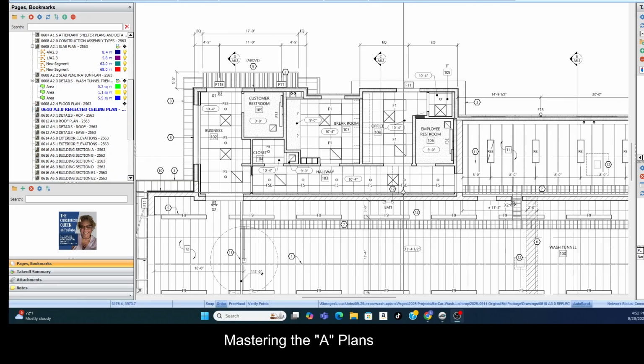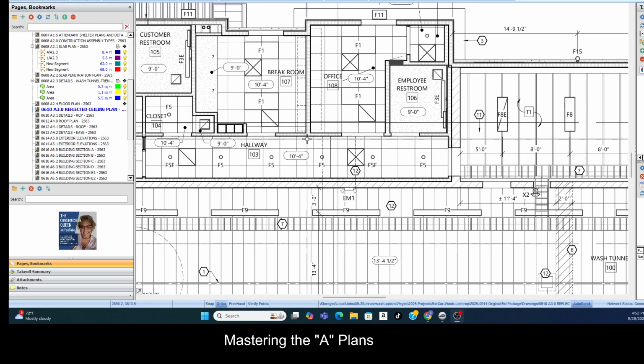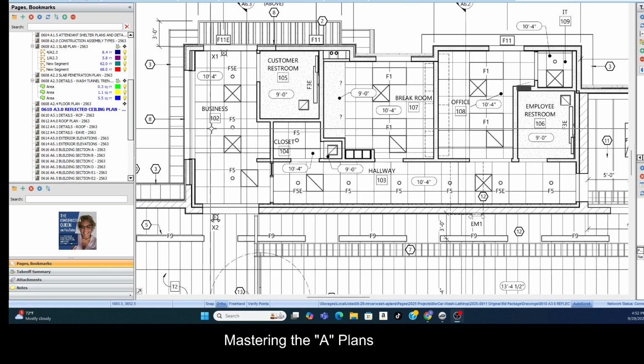It reflects everything in the ceiling, so each of the professionals know. It's like, oh, okay, in this room, I have two supply grills and one return grill. Oh, in this room, I'm going to have to adjust or fit one, two, three of my tiles to fit the lighting. Or because it's a 2x4 light, right? Then I won't need a 2x4 tile in that room. And so they'll do their math and they'll determine for each of their individual finishes for that ceiling.